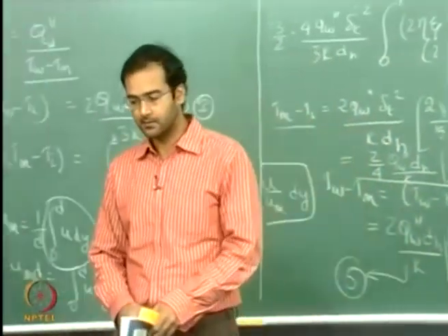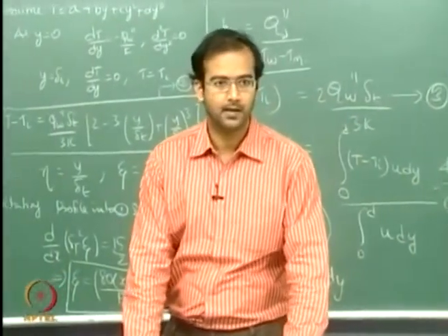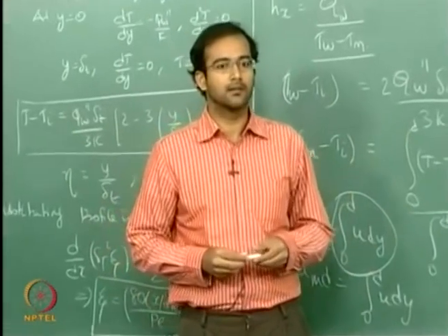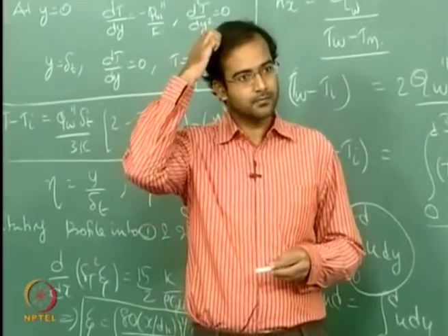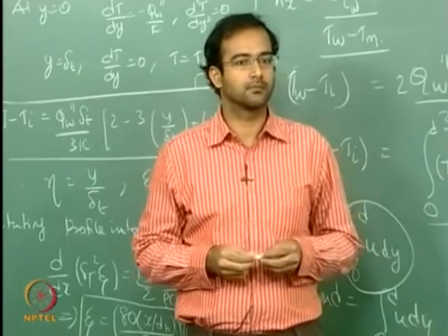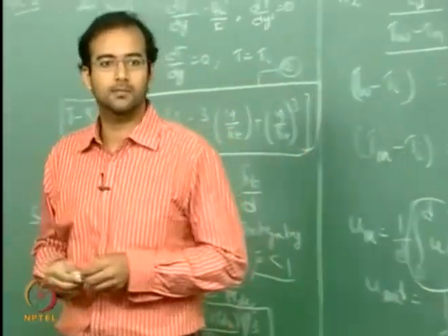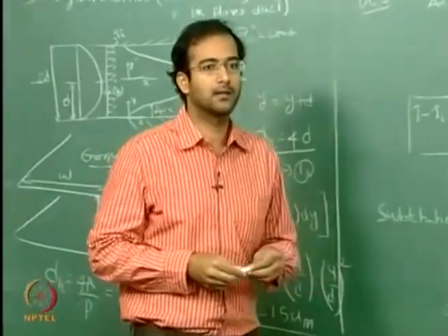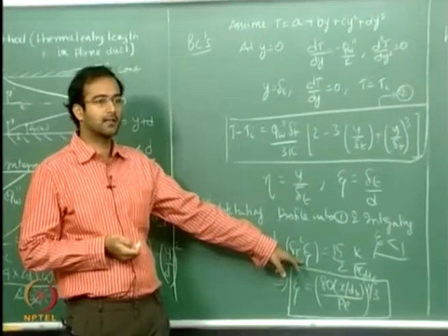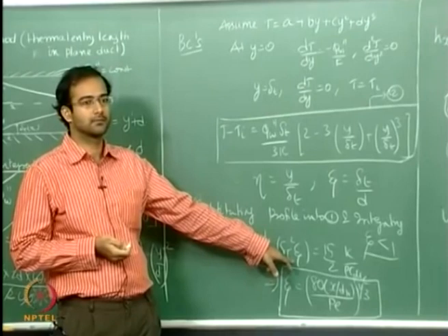This is because the integral method is not valid for the asymptotic limit. Why? The boundary layer is merged, so the boundary layer approximation is not valid anymore. And the other thing, in the energy integral we have neglected the higher order terms of zeta.